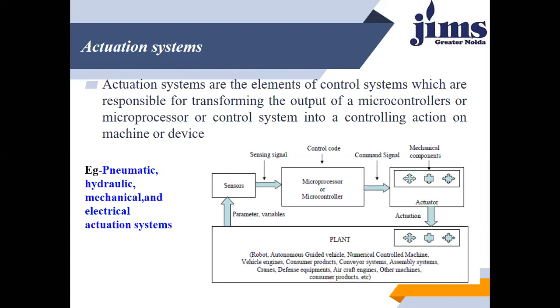If you go further, it is possible to generate high gain in force and power amplification by the use of this hydraulic system. We can easily amplify the power in case of the hydraulic system, right? Then hydraulic systems are uniform and smooth, and this can generate stepless motion. They are not having any steps, and variable speed and force to a greater accuracy. So the accuracy of hydraulic system is too high.